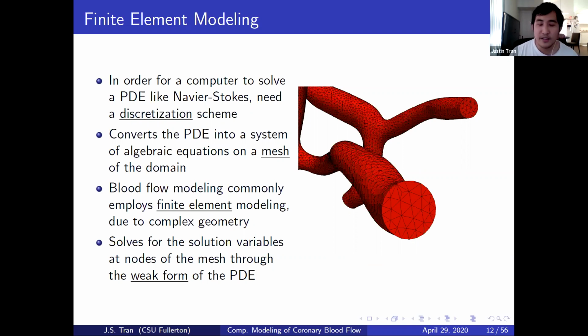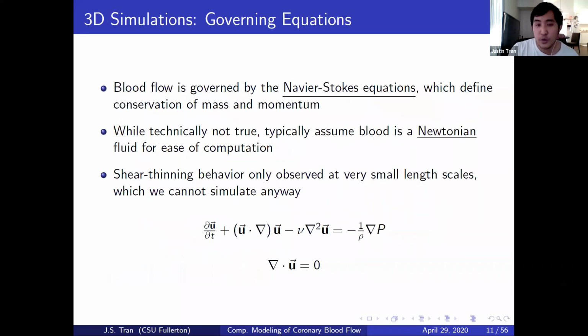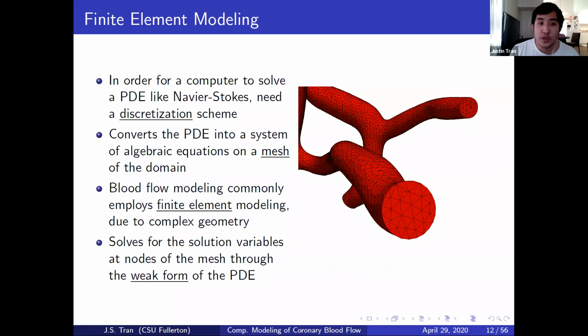I'm not going to get into the math of finite elements. For 410, we spent basically an entire semester doing that. But the upside is that through the finite element method, we take a partial differential equation, which is the Navier-Stokes equations here, and turn it into a system of algebraic equations that we solve on our mesh. The nice thing about algebraic equations is that there are a lot of methods computers know to solve them. So if we can get our PDE into that form, the computer will have a much easier time simulating it.